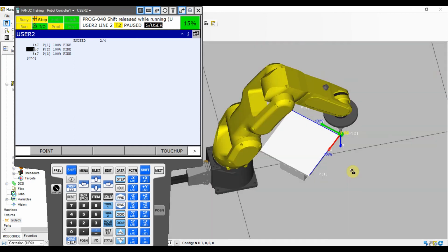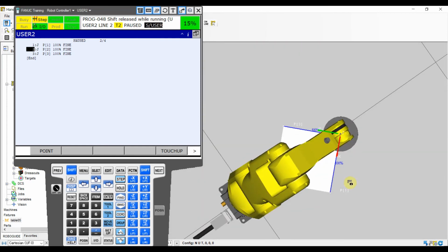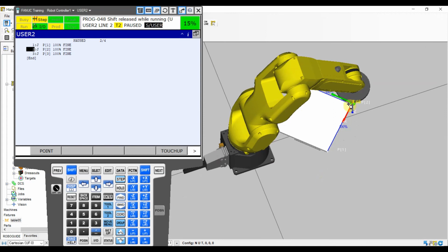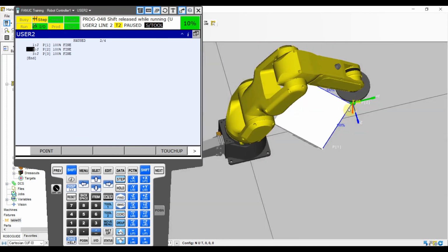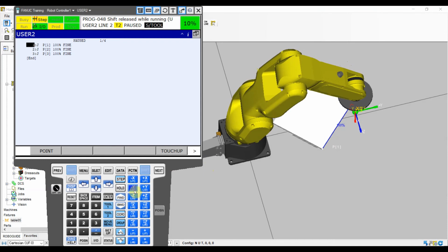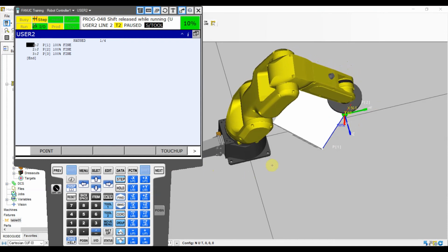So it's easier for us to operate on that table, because guys, if you want to move according to that edge using any other frame, even the tool frame, it's not going to be possible, because that's your tool frame. How are you going to move straight according to that line? Well, you can, right? We can go Z plus, then we can go Y minus. Okay, we got here.